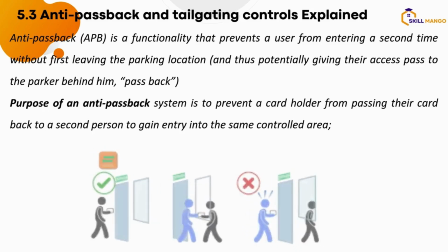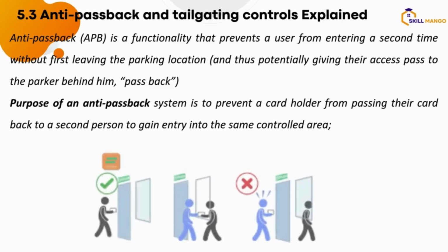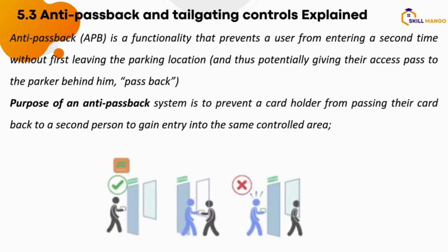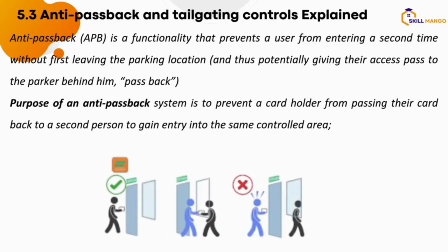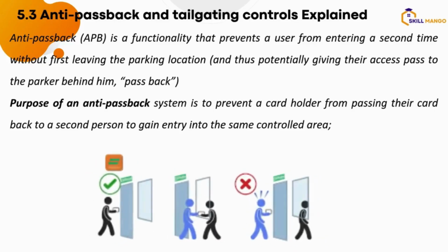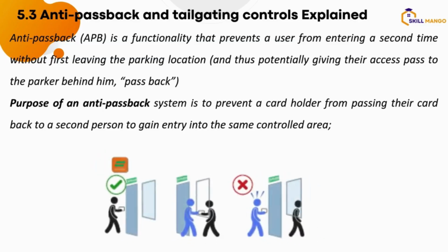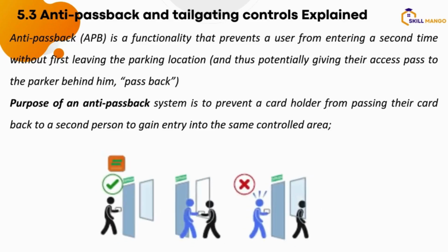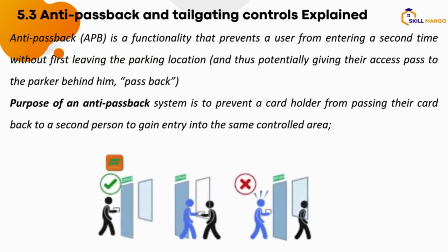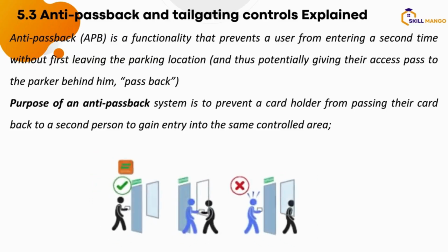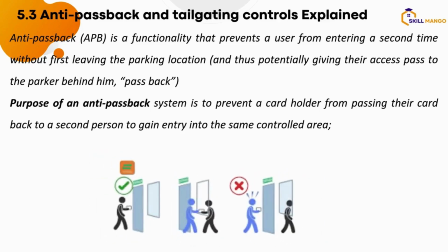Okay, so what is anti-passback? Basically, if you deploy an installation for door access control, you usually use a reader in, then exit button out. Meaning that when somebody is coming into the building, they flash their card at the card reader, or they use their biometrics, their thumb or profile, or they use their face or PIN, to gain access to the facility. When they are going out, they use the exit button.